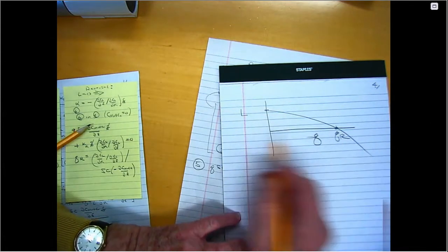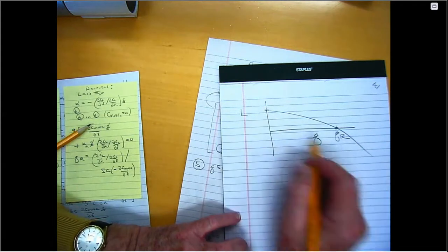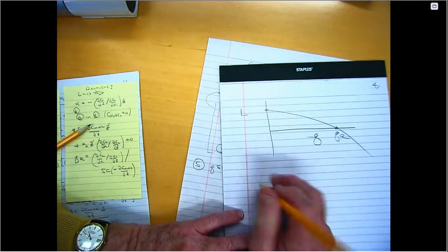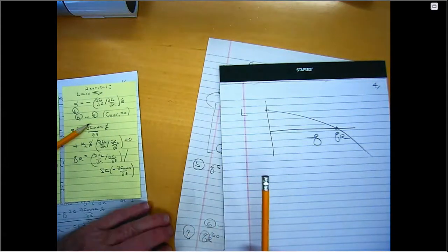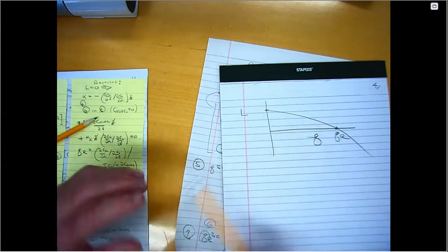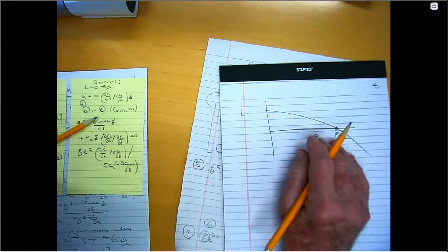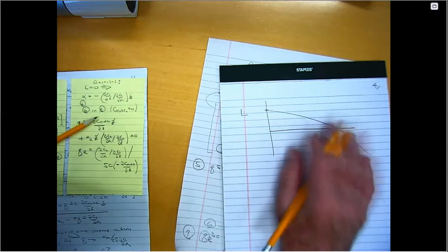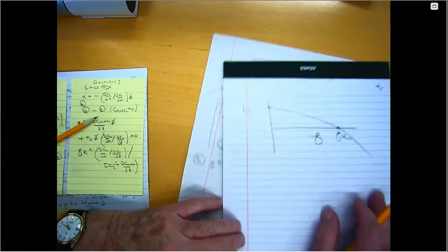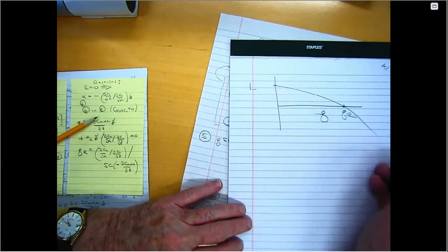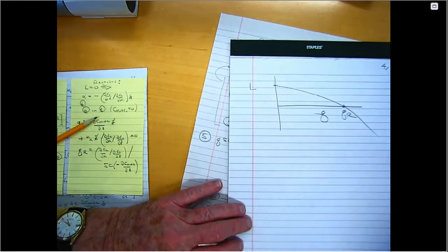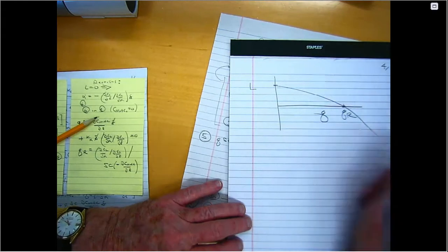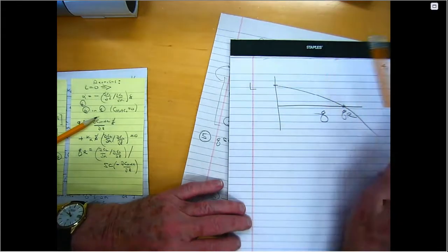So, if Boeing or Airbus or Lockheed Martin or whoever would probably do this. I probably should have done the more elaborate analysis, or at least assigned it as homework. Well, we'll do that later. You have done enough homework already. But we can compute the entire curve, right? The entire curve would be to solve that equation for alpha in terms of delta, and substitute in the expression for lift. It wouldn't be a terrible thing. It's just more accurate.